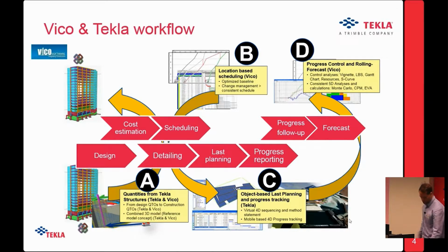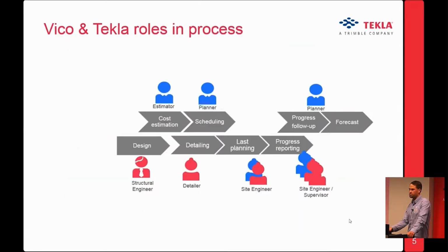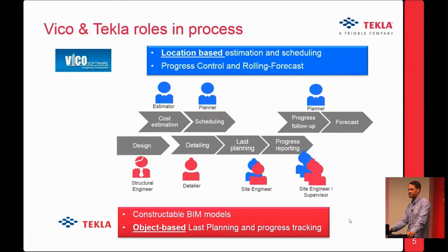And also why we are using both softwares at the same time in parallel is that, like we heard, location-based scheduling is based on locations, and what we're doing in Tekla is based on object levels. So each precast element, each cast in place structure is our own object, so we can do even more detail level planning.